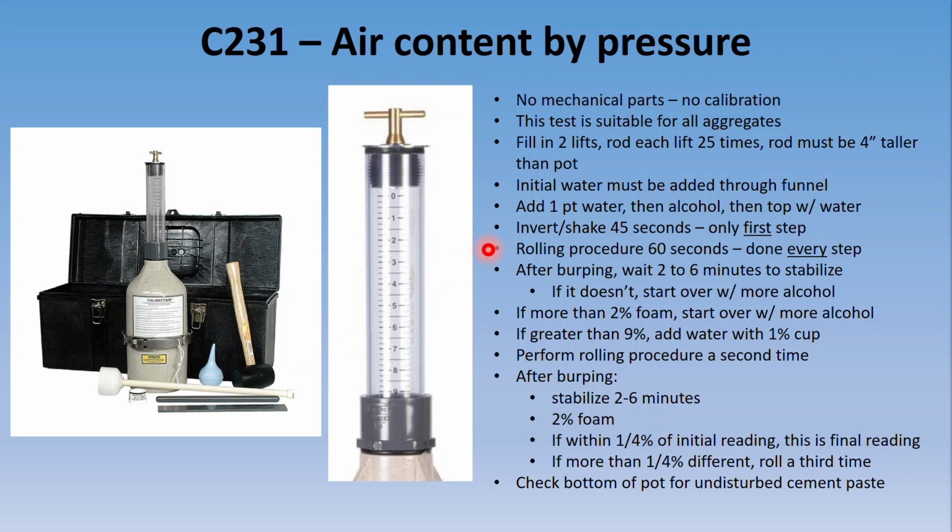So after you've rolled it for your 60 seconds, then you're going to set it down, pop this cap off, and burp it. You're going to let that air out, whatever air you released from the concrete here. And then you're going to wait minimum 2 minutes up to 6 minutes for that water level to stabilize. So you're going to watch the water level here in your neck. It started up here at 0 before you did all that agitation. Now it's going to be down here somewhere.